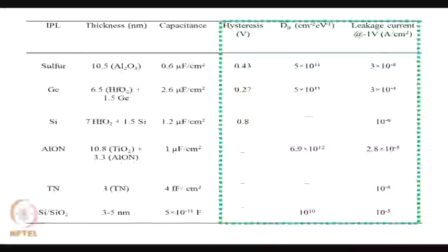So, if we conclude today's discussion, one thing is the application of the low K dielectric material in the RC interconnection network system. We must have the RC value as low as possible, and this low value of the delay, which is the product of RC, is coming from the value of the C.